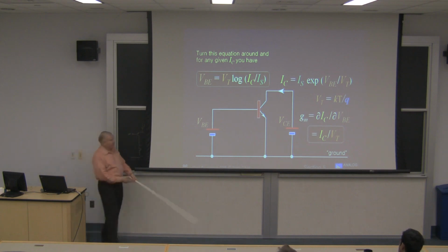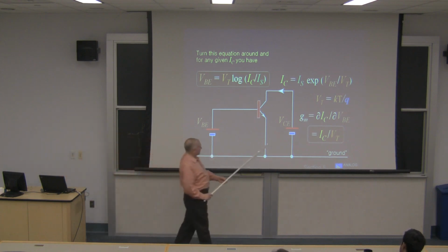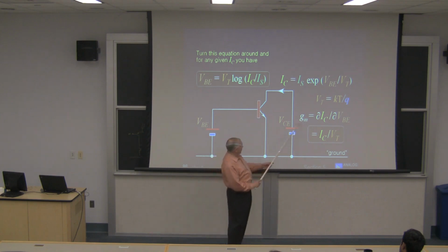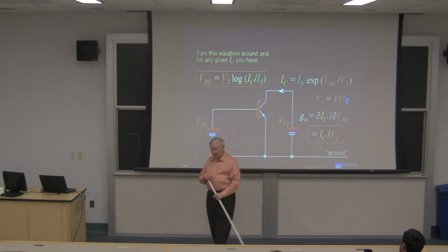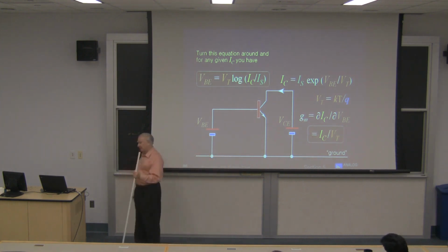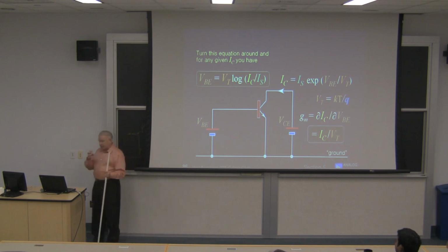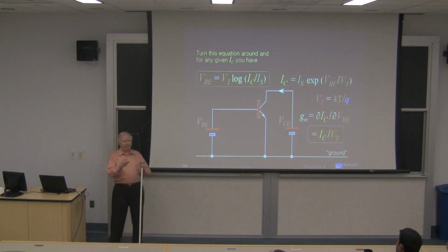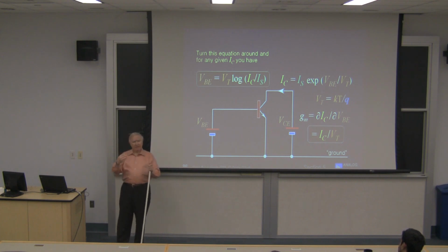But then getting back to another wonderful thing about the bipolar transistor, excuse me for the enthusiasm, the gm is just the collector current divided by kT/q. And again, it doesn't matter how you make these parts. That's the nature of a junction device, because its roots go deeply back into physical phenomena in a way quite unlike the way we have to deal with channel conduction in an MOS transistor, which is very much an empirical affair.